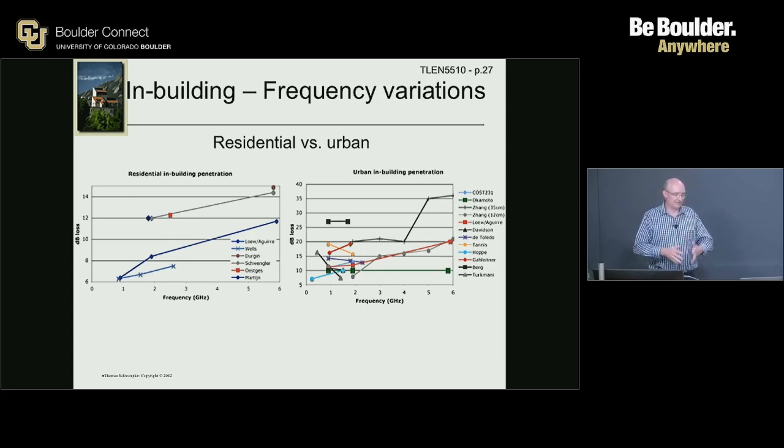You have to say, I measured this with a horn facing 90 degrees on every wall, and I measured that. Or, on average, I put a base station here and measured down the street about 100 meters, every home on average with an increasing angle of incidence, and my result is this. The point is, it's very difficult to compare apples to apples in those papers.